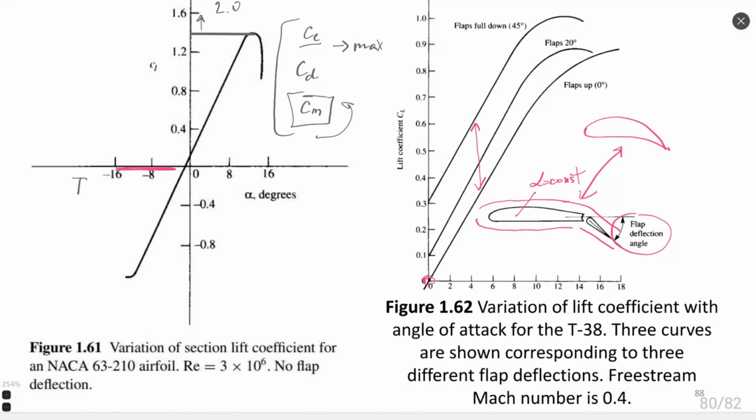The main part of the wing has a constant connection to the fuselage, so it has a constant angle of attack, and the flap is rotating, changing the lift coefficient by a negative or positive value. With the change of lift coefficient we have lift changing, variation of lift, not just lift coefficient, right?